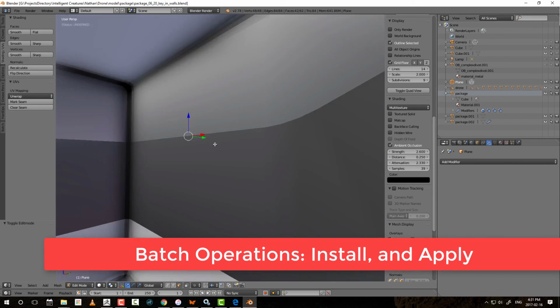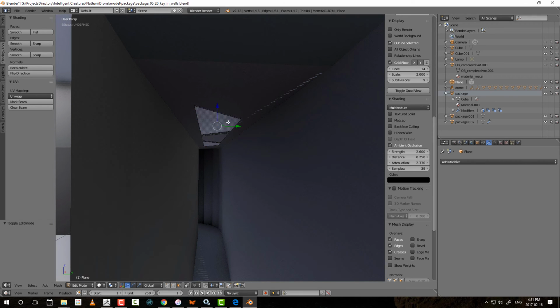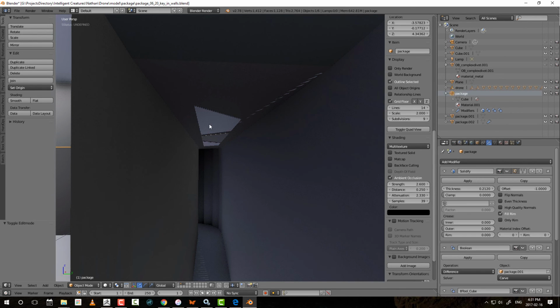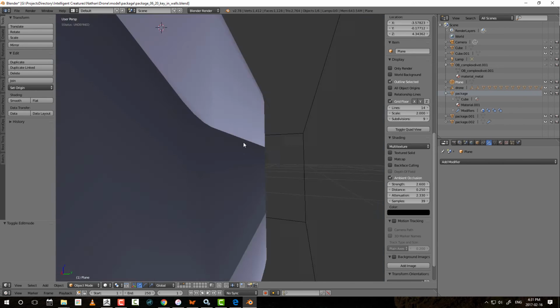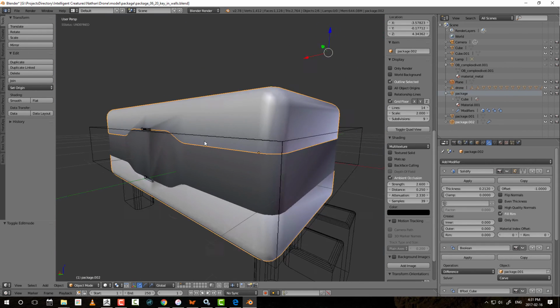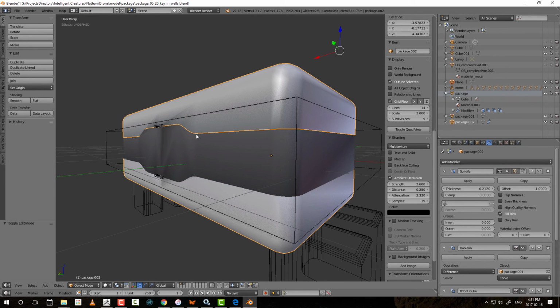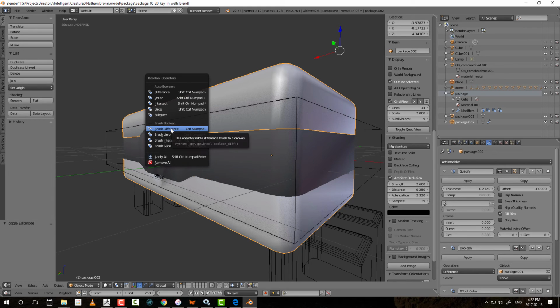So now it's time to actually do the Boolean operation on these. First of all, you have to be out of edit mode, so press Tab to exit. Select the key first, and then navigate out, and then shift and select the top portion, like I am here. And now, Control Shift B, and make a difference.